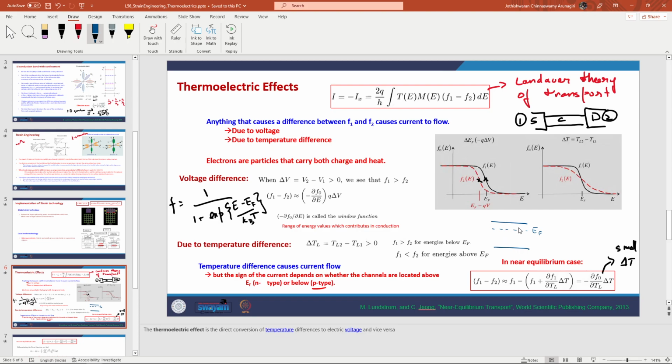Now for an n-type material, if we increase the temperature, of course the Fermi function is going to change, but additionally, another thing that we can infer is that more electrons will jump from the donor level onto the conduction band. I have the conduction band and the valence band, so increasing the temperature will imply more electrons can jump up to this level.